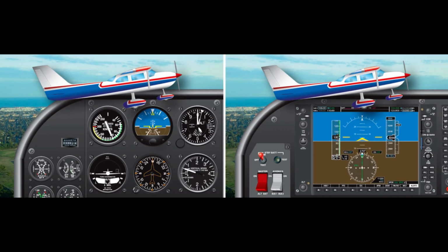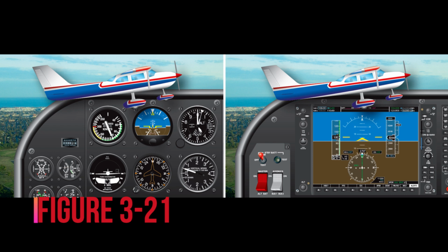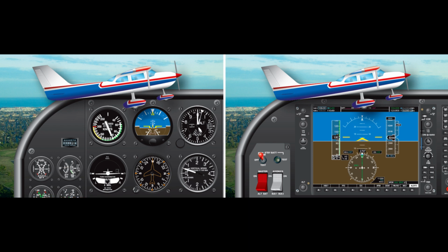To return to straight and level flight from a climb, it is necessary to begin leveling off prior to reaching the desired altitude. Level off should begin at approximately 10% of the rate of climb. For example, if the airplane is climbing at 500 feet per minute (FPM), leveling off should begin 50 feet prior to reaching the desired altitude. The pitch attitude should be decreased smoothly and slowly to allow for the airspeed to increase. A loss of altitude may result if the pitch attitude is changed too rapidly without allowing the airspeed to increase proportionally.